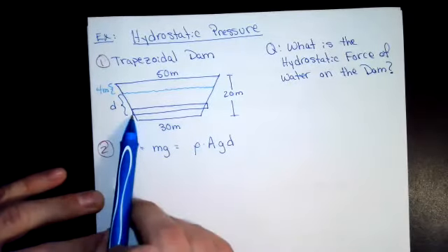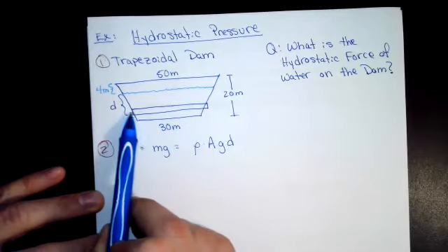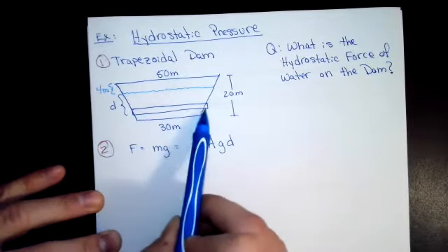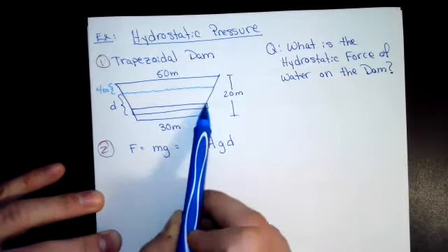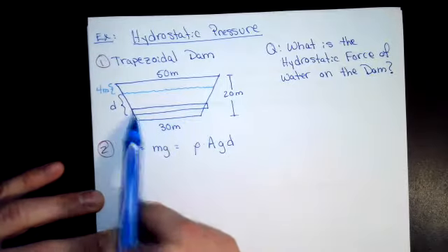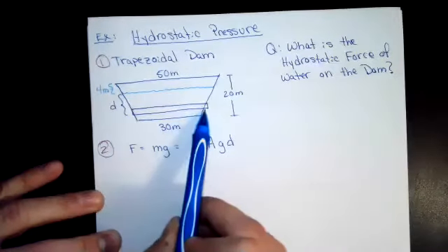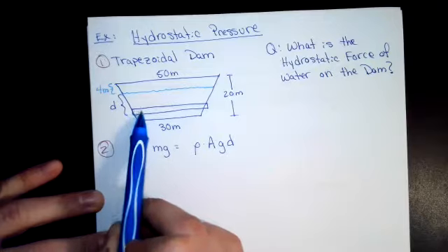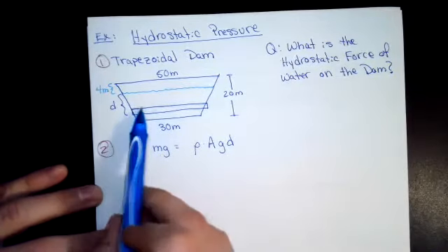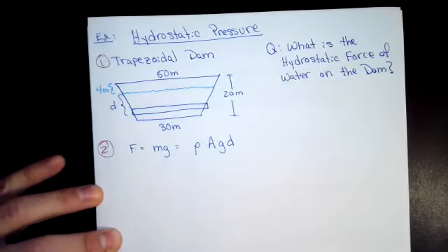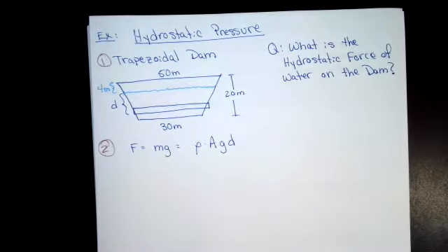And then at that fixed depth, since we want to slice it horizontally again, we'll have a fixed depth, and then we can figure out the total area of that to add up all of the force on that. And we just have to multiply times rho, the density, and gravity. Okay.